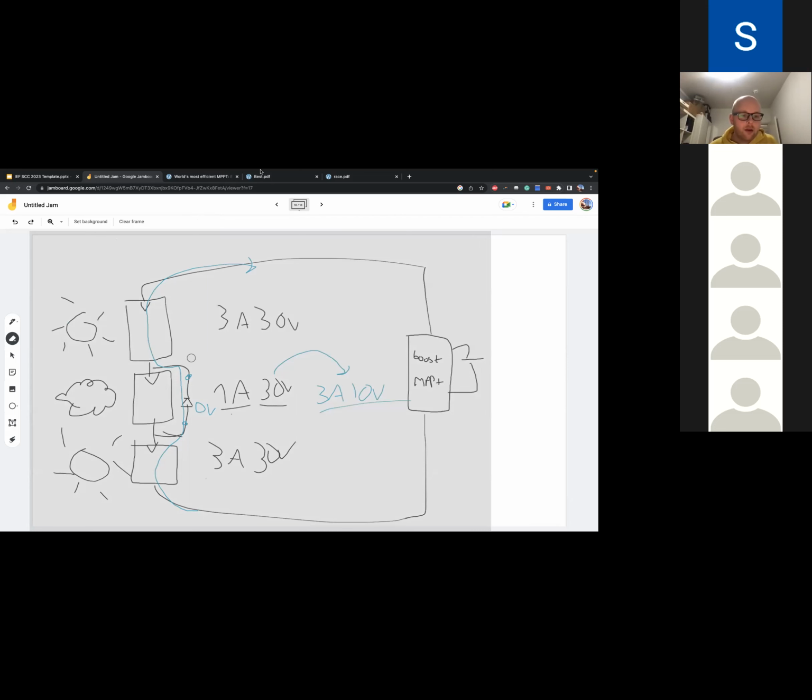Yeah, instead of this diode thing, we should get rid of that, and we should just connect a buck converter. Let's see here. A buck converter is not that difficult, well, in my world at least. But it needs a capacitor as well. But maybe you can use the one of the solar cell.